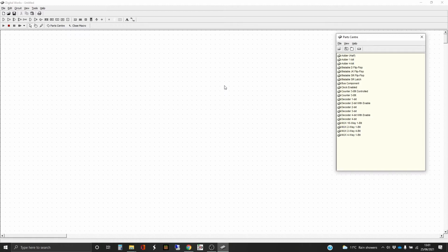So we're doing registers, and we've done some discussion as to the problems to do with reading and writing to buses for registers. Registers are small memory components that form part of the CPU. And in this video, we're going to finally get to actually make something again, and we're going to make a 1-bit register, which can then be multiplied up to make larger registers. So the basic component we're going to use for this is a D flip-flop, which is the data flip-flop, which is able to store data.